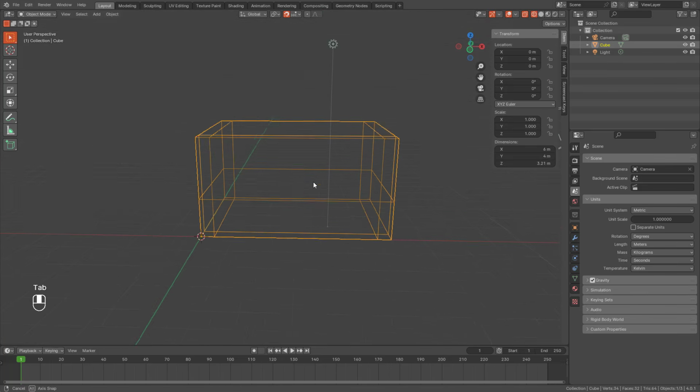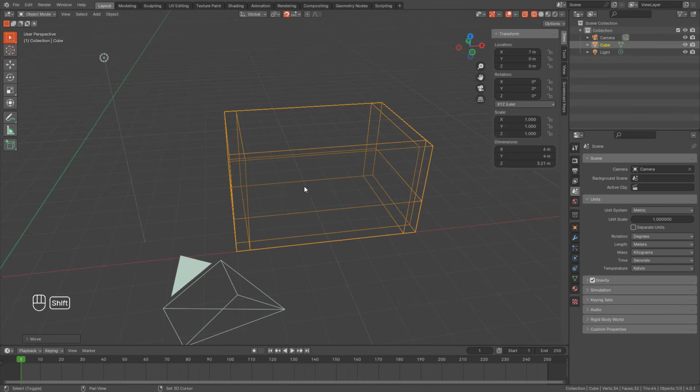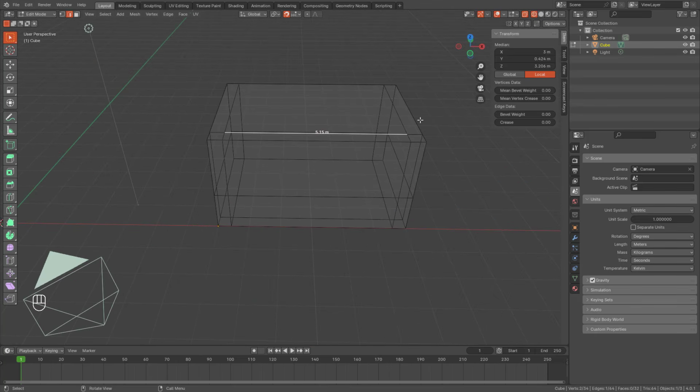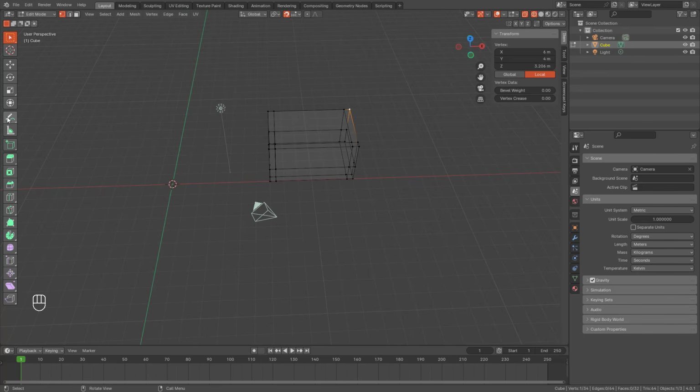So if you move this building somewhere, and the object origin moved, now if I select, for example, this vertex in the X direction, it's 1, 2, 3. It should be somewhere around 13 meters, right? But look at this. It is 6 meters. It's not 13 meters, because it is calculating from the origin of the object, which is here. So if you change it to global, then you will see that it's 13 meters away from the origin.